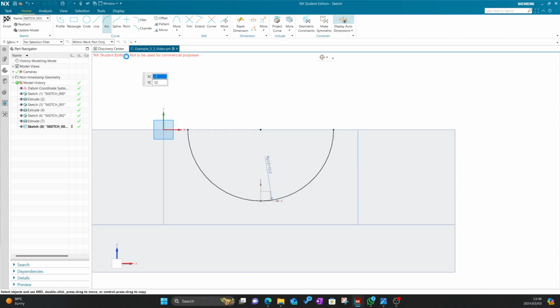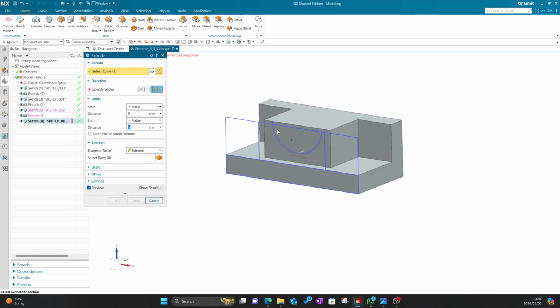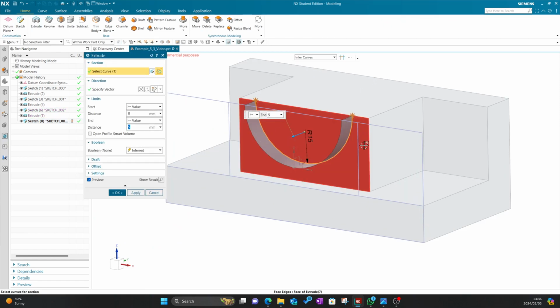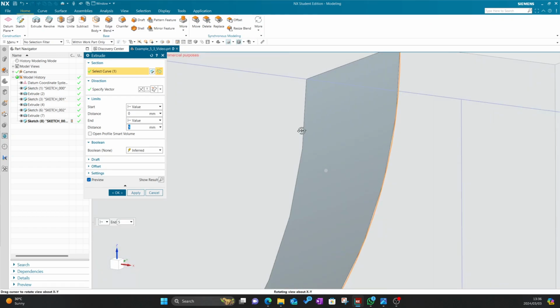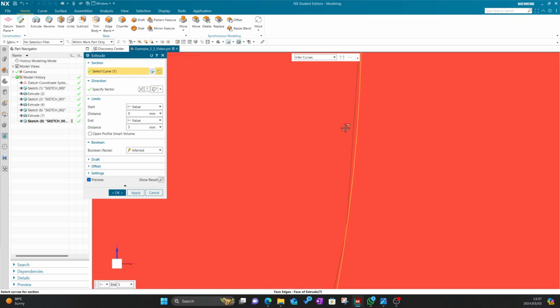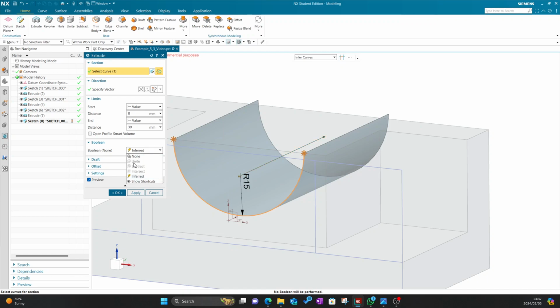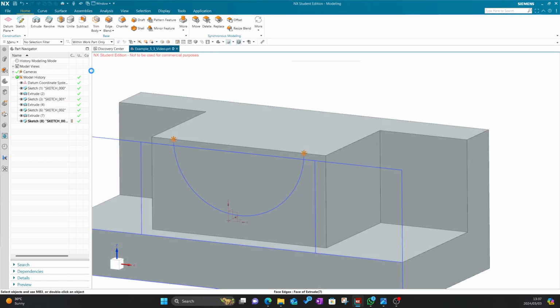And now you'll see you cannot extrude just a line. It needs to be a closed loop. So if I say finish now and I say extrude that feature, it will create a zero thickness extrude, and you cannot actually see that it's zero thickness. But that's not what we want, and you cannot extrude with that. You cannot subtract. You'll see there's no option of subtracting or uniting, because you're not creating a three-dimensional model, you're just creating a zero thickness sheet. So I'm going to cancel this.